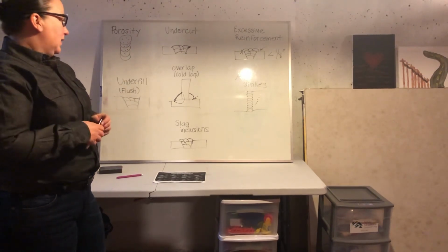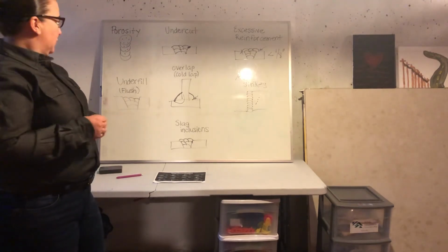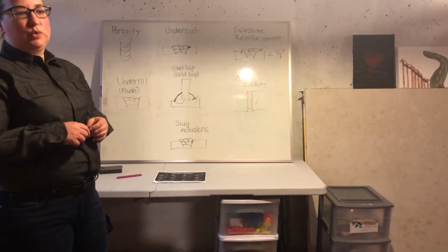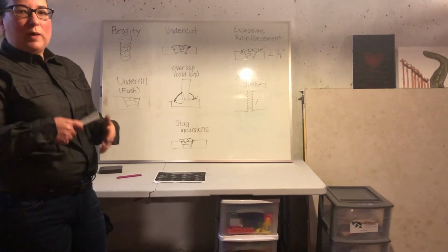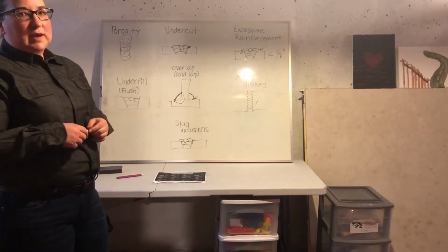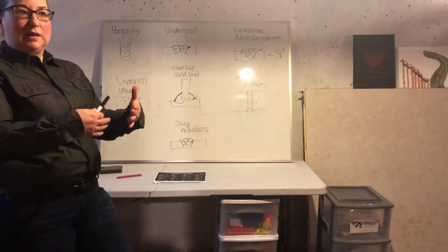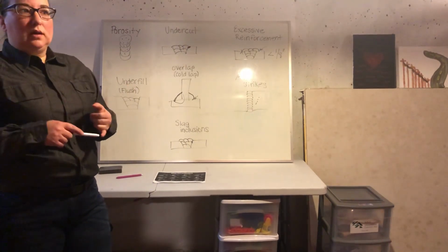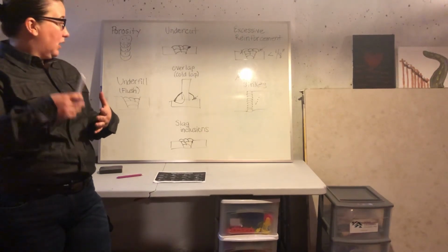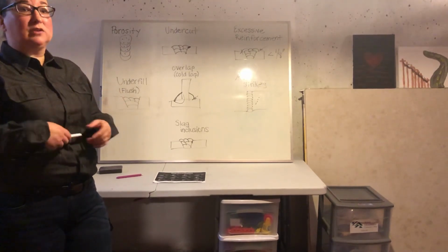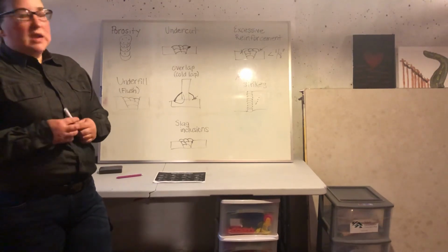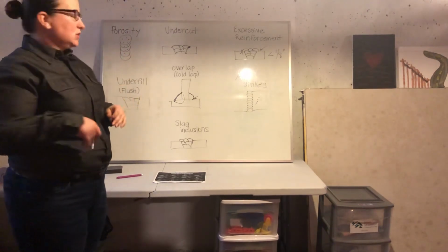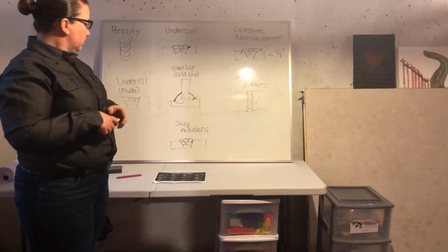And then a simpler reason to get those slag inclusions is actually from people just failing to clean in between welds. Everyone likes to weld, but we do have to take that extra step, cleaning before we weld and cleaning interpass, whether we're using mechanical means, our hand brushes, our chipping hammers, our files, or a wire wheel. So those are some different things that we use to clean. There are also needle descalers that we can use to clean those that usually run off air.